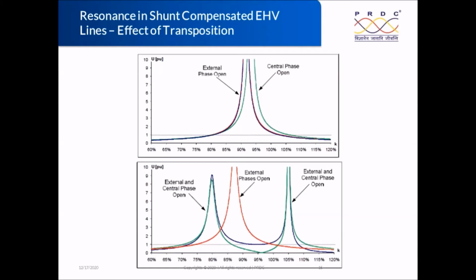If it is saturated, it may reduce. Whatever we have seen, like a theoretical resonance point, it will be infinity, but with saturation representation, the voltage magnitude may be reduced to 2 per unit or 3 per unit, even at the ideal resonance point. The next, saturation knee point.